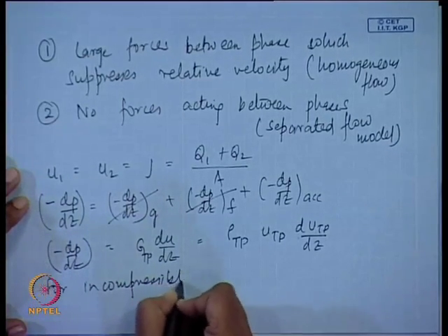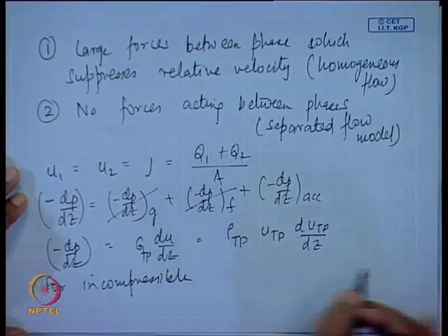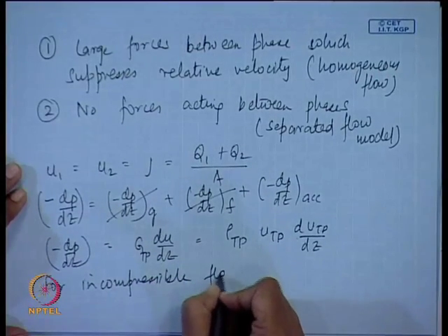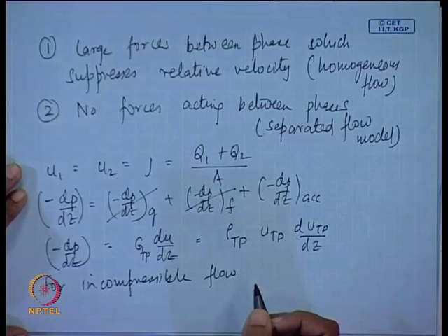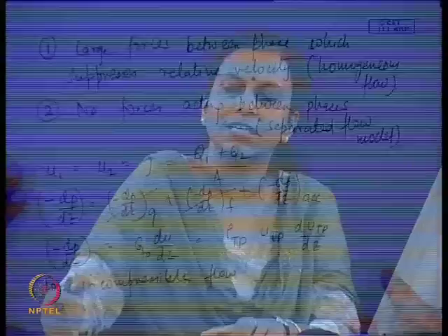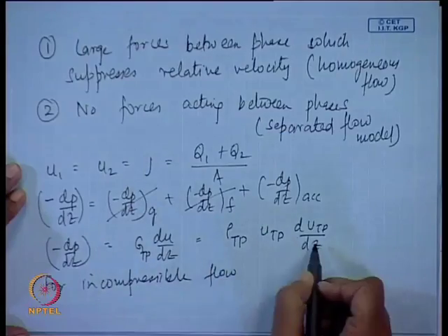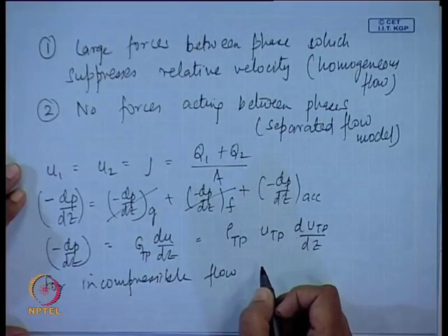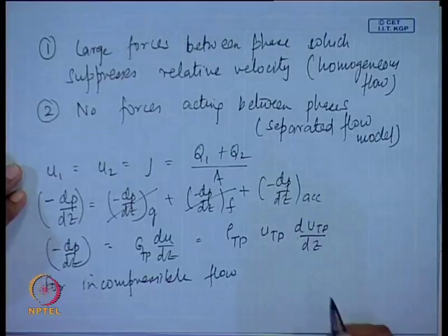constant and it has been given and the pressure is not expected to fluctuate much. So, you might be given such problems in your exams where you have to make rational assumptions and then progress, depending on what type of assumptions you made. Even if the assumptions are wrong, but if the logic is correct, you will be evaluated. So, remember these things, it will be much more analytical as compared to anything else. Under this circumstance we can assume that it is incompressible flow, because water is anyhow incompressible. Air for such a small pressure drop is also going to be incompressible.